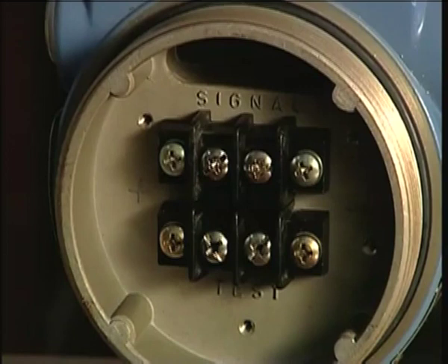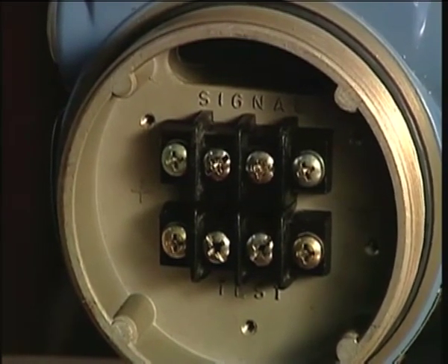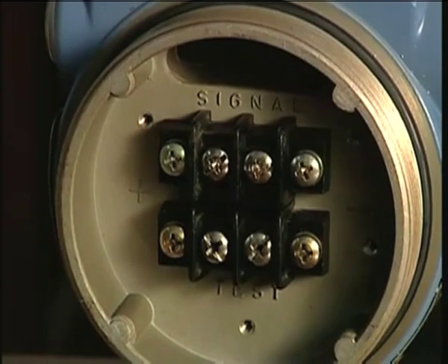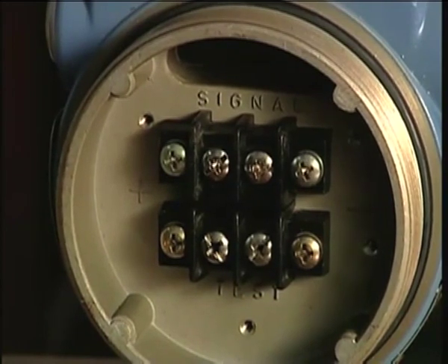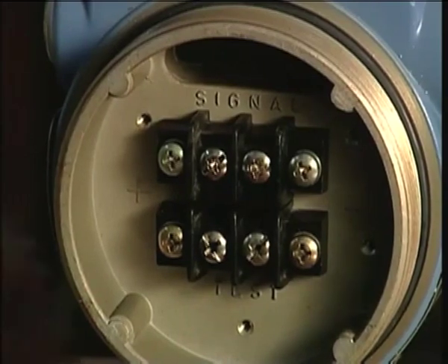First of all, this circuit will measure the variation of that capacitance, and that variation of the capacitance will be converted in terms of current, 4 to 20 milliampere of current. So ultimately, this 4 to 20 milliampere of current will be calibrated in terms of flow, and the output signal we can take from this side. We can open this side and see here.